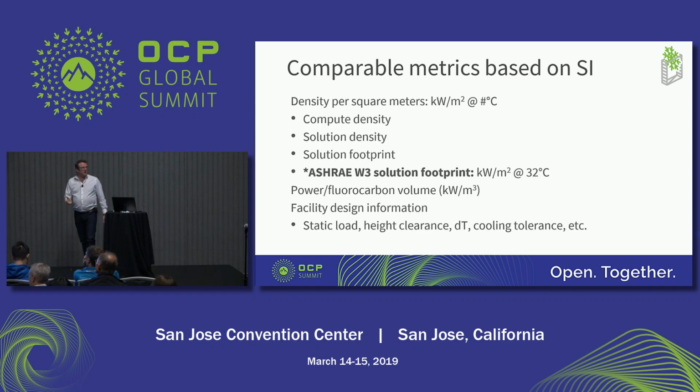And still those figures are then fairly vague because, especially with immersion, the density is greatly influenced by the temperature of cooling. So a 100 kilowatt tank, if you apply 12-degree cooling to it, you can achieve much higher densities compared to 40 degrees Celsius cooling. But from a TCO perspective, the chiller unit that you don't have to buy for 40 degrees Celsius gives you an additional TCO benefit, whereas the incredible density you can achieve with lower temperatures gives you a density advantage. Now, and this is why these figures are important.